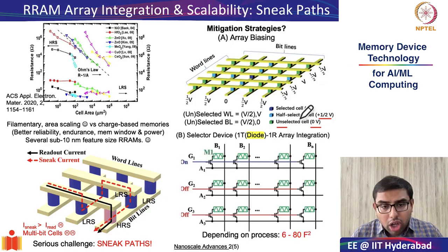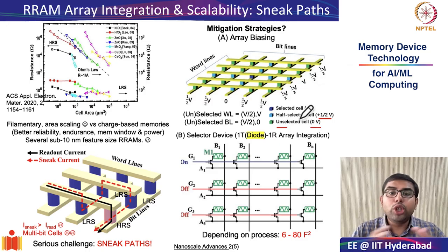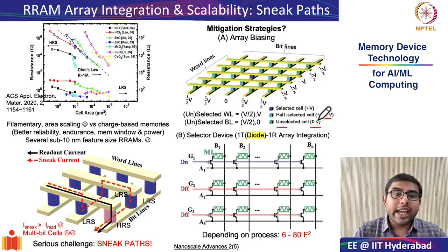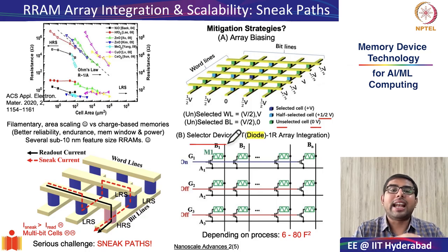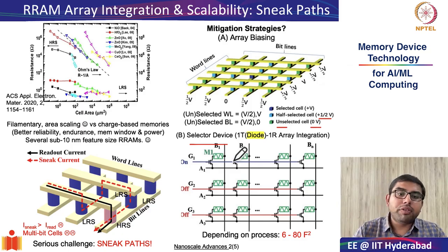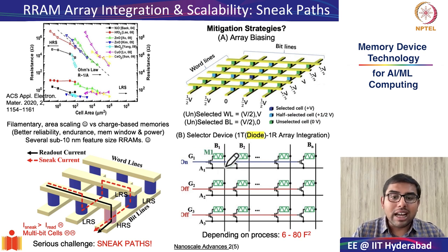However, the methodology which is universally used in the integration of RRAMs into large arrays is adding something called the selector device. The adding of a selector device is something we have seen even in PC-RAM technology, where the PC-RAM was integrated on the drain of an access transistor. This is also what is done in the case of RRAMs, where RRAMs are integrated in 1T1R arrays.